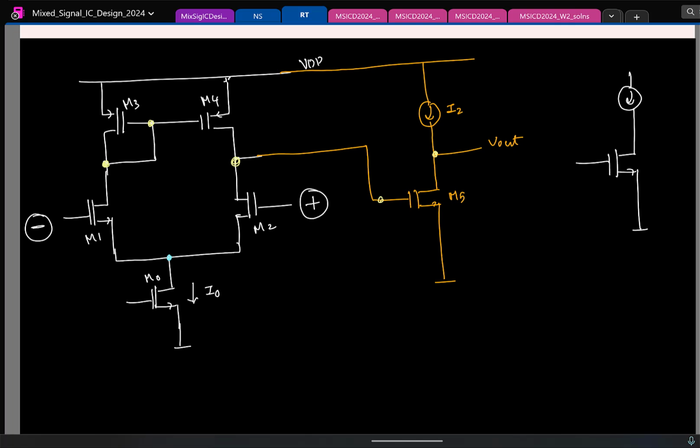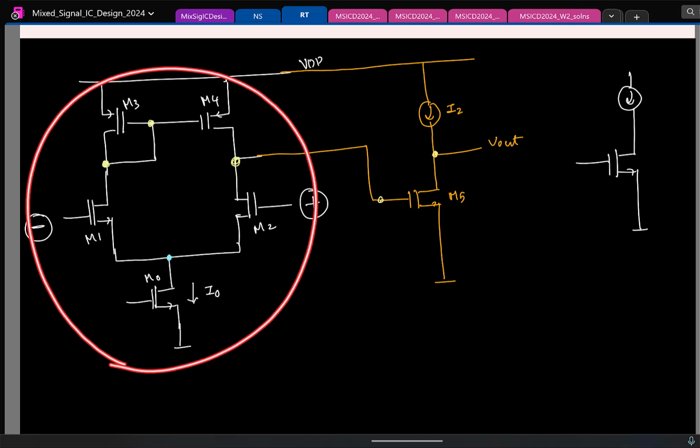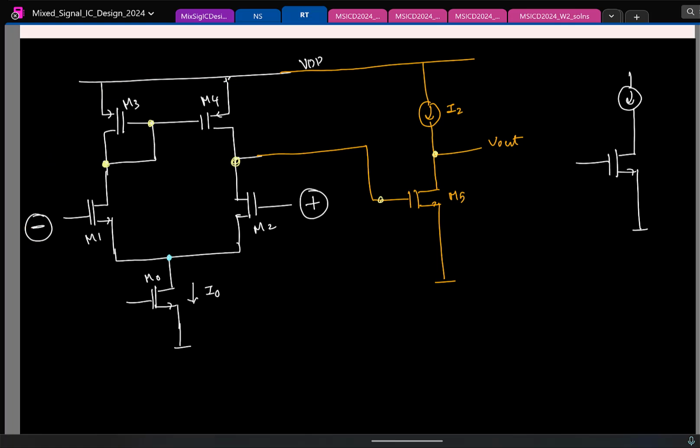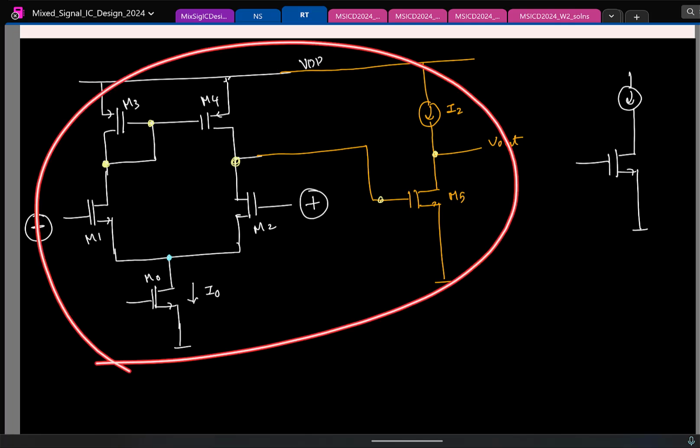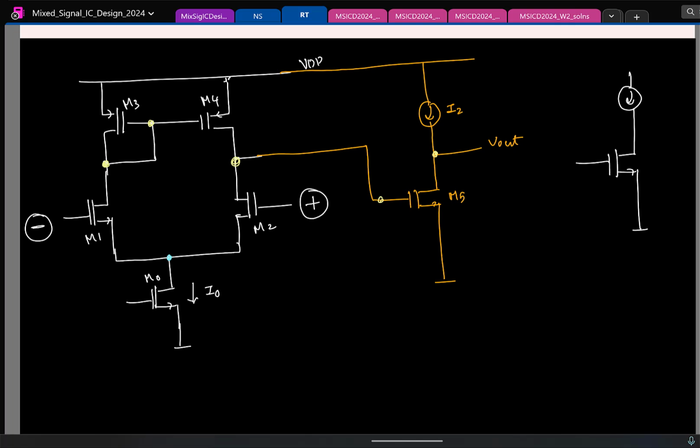Did we see a similar situation somewhere before, where the operating point was not getting set properly? For M4 in the 5 transistor OTA. So what was happening finally there? So here again, this is an op amp. An op amp, remember, is never meant to be used in open loop. So where should I use it? In negative feedback, some kind of closed loop system.